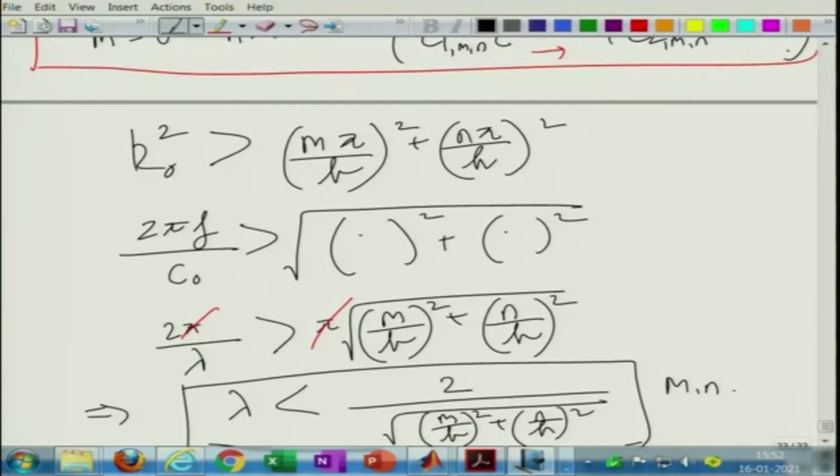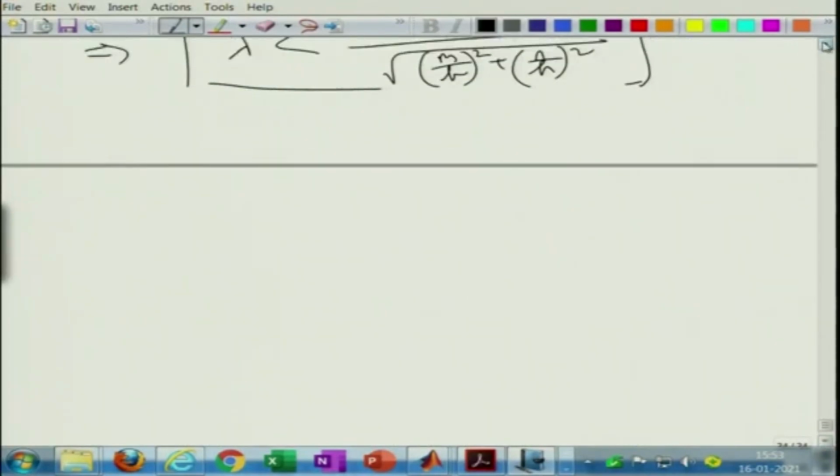So, at low frequencies only the planar wave is important, nothing else. Of course, if we consider the first few evanescent modes, our solution accuracy might improve for some muffler configurations at low frequencies, but only beyond the first cut-on frequency we may have to consider modes other than the planar wave mode. So, the idea is that only the first few terms in the modal solution are important, it is not necessary to consider all the terms. Okay, so that is of great importance here.